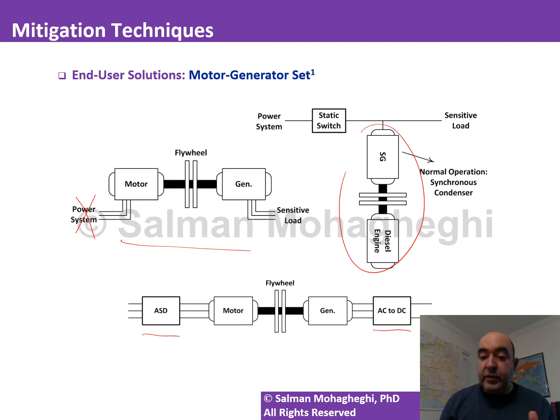The benefit is you can let the generator run for a longer period of time, because regardless of how much the frequency drops and how much the voltage drops, by using the proper switching of the rectifier, you might be able to still maintain an acceptable level of voltage to the load. So loads might actually be quite sensitive to drop in frequency, but using that rectifier, you're not worried about frequency anymore. You're just worried about getting the right voltage magnitude. So this basically allows you to utilize more of the energy of your device than before.